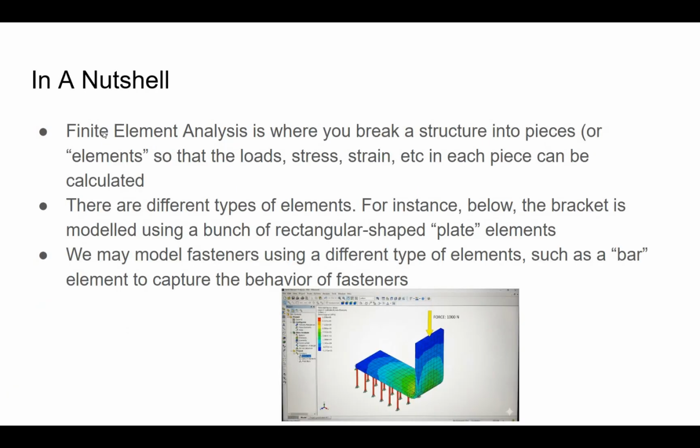So in a nutshell, finite element analysis is where you take a structure and you break it into pieces, and these pieces are called elements. The purpose of this is that you're trying to formulate a model so that the loads, stresses, strains, and other phenomena, they also do this with thermal, which we'll get into later, but for mechanical loads, stress and strain get calculated in each piece so that you can see where the stresses are in the model.